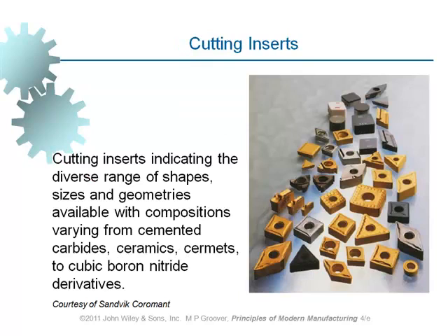Well, inserts. Here in this slide we can see different shapes of inserts which are often used in cutting tools. Generally, we can divide cutting tools into different groups. One of the most commonly used groups of cutting tools is high-speed steel cutting tools, HSS. Have you heard of HSS cutting tools? High-speed steels. In high-speed steels, we don't make use of an insert because the whole material is of high quality and it is the one to be used for cutting the material.